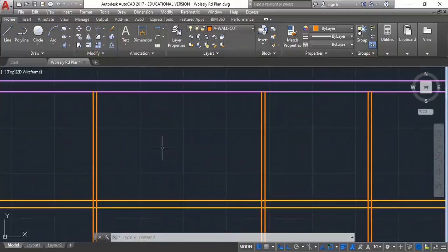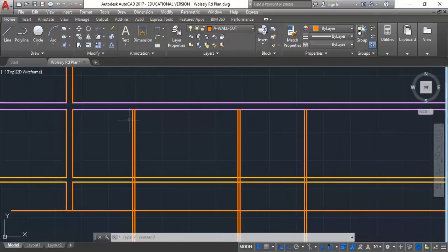So here now I can see the wall without the doors being cut into them, but then I can just offset the door height. So are you just using standard door heights? 2100? Yep, not 2 metres, good. Okay, so I'm going to offset 2100. So the sliding door? Yeah, same. So just do 2100 for those as well. Oh yeah, I'll do that too, yeah.